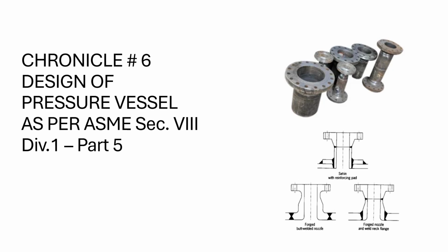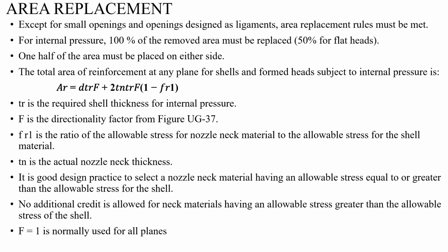But what if the diameter is more? Normally we say that if the diameter is more, we have to put the reinforcement pad. But that is not always the case. What we have to do is check whether, without the reinforcement pad, our nozzle design is adequate or not.